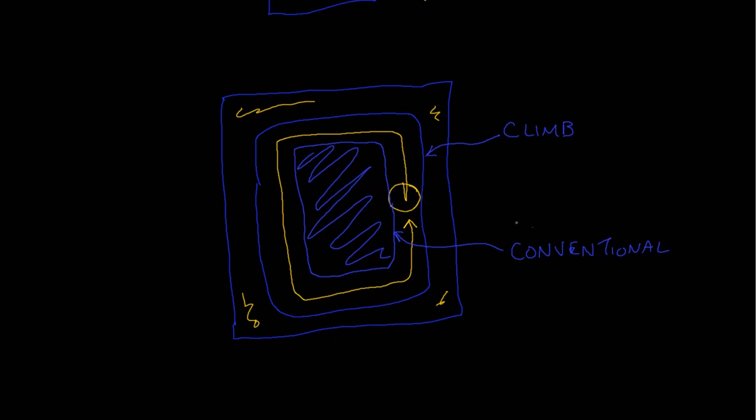So it's somewhat of an inevitability that you would end up conventional milling the sacrificial material, and so that will decrease the tool life in pocketing, compared to, let's say, just going around the edge of the material. So you're kind of doing both in this scenario. You're climb milling on this side and conventional milling on this side.